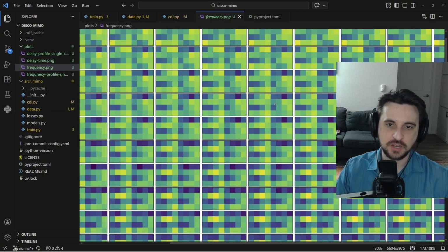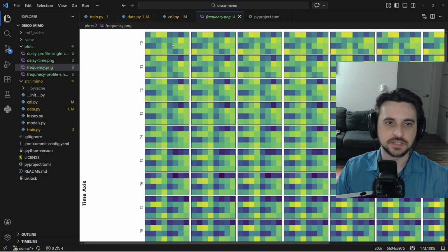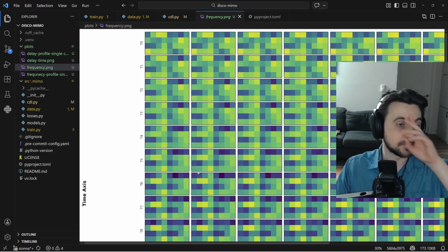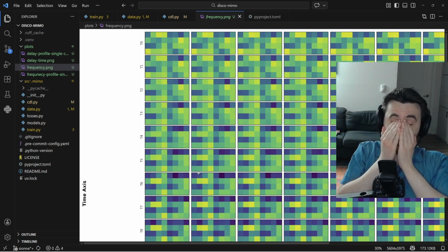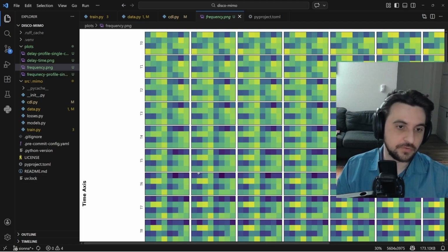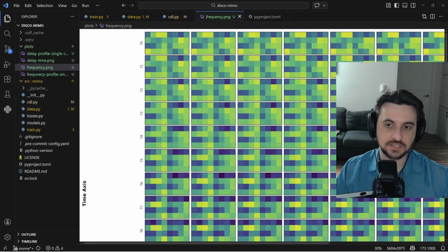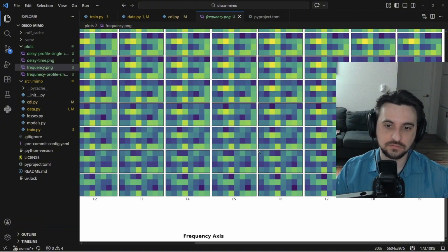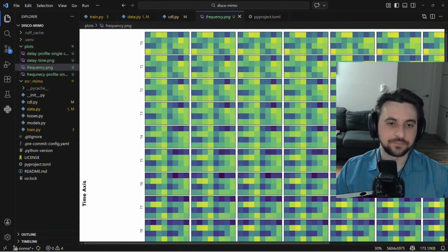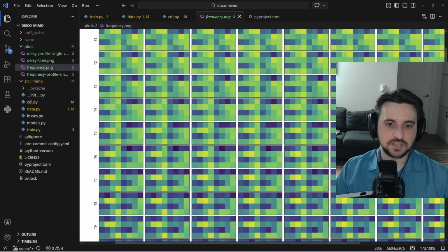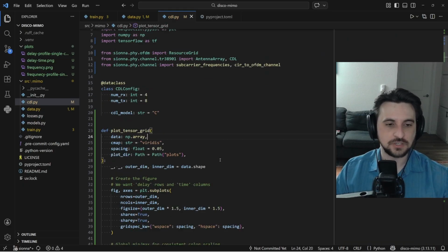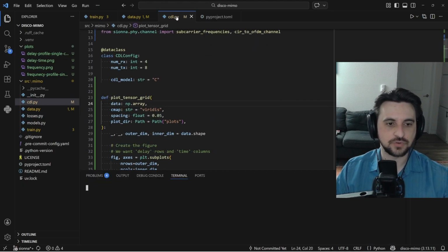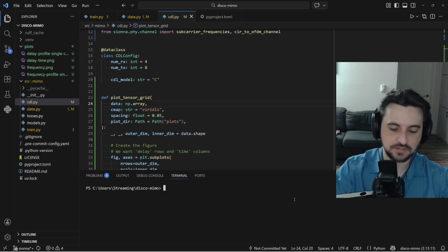model on, right? So this is a pretty complex MIMO channel now because there's a lot of scattering, right? There's no more groups of antennas that are sort of clumped together. It's 4 receive antennas, 8 transmit antennas, and the gains look different. So then we're just gonna sample this grid, and that's it. Now we have the batch dimension, we have everything, so we can actually generate the training and validation data set of tens of thousands of channels.